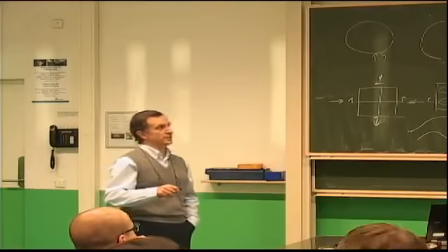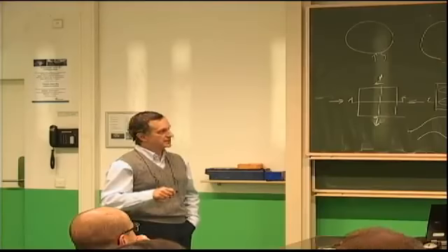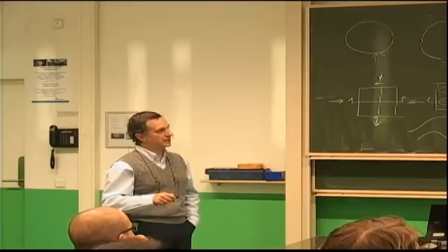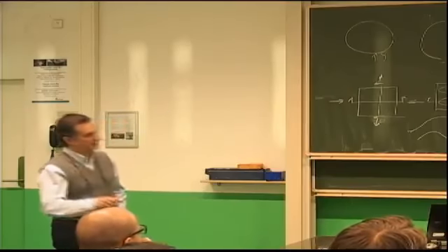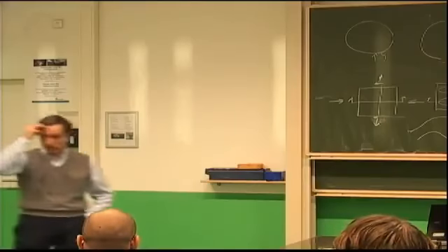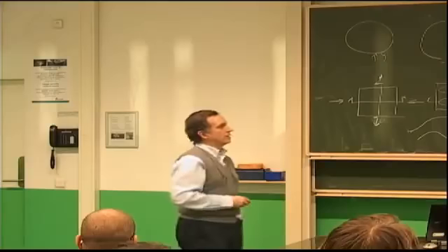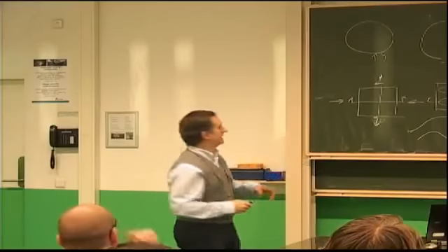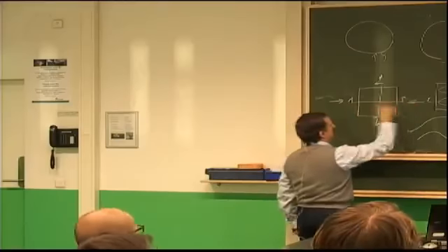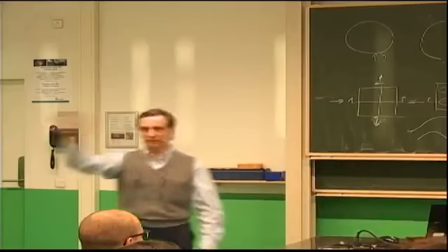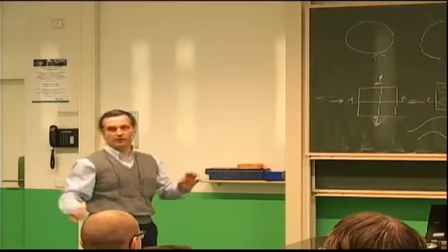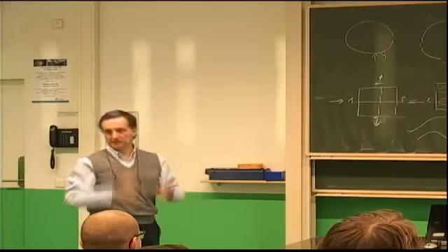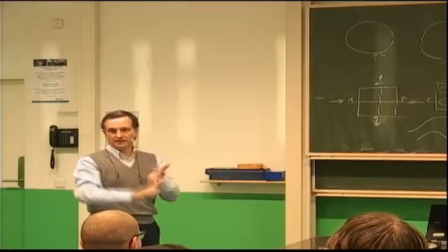In the case of uniaxial compression, it's slightly easier. Once K disappears, N appears only in the numerator, which means if I'm trying to minimize this, since all the terms in the numerator are positive, the smallest value of N, which is N equals 1, will give me the buckling load. So if I have uniaxial compression of a plate, then the number of half waves perpendicular to the load, in this direction, is 1. It will only have one half wave. So you can impress your friends by telling them you can derive or prove that it will always be 1, no matter what the stacking sequence is, as long as it's symmetric and D16 and D26 are 0.